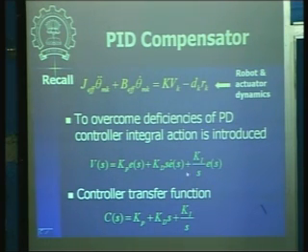integral control action. What this action does is basically take the error value and integrate it over time. In the steady state, imagine you have this constant steady state error value, and you are integrating that. Integration is nothing but this area. As time proceeds, this integration is going to increase, this area is going to increase. Because you are now applying that to the robot control, the error will slowly start decreasing.